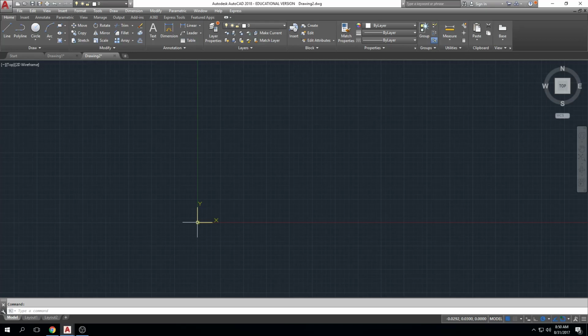When we look at our AutoCAD model space and we have these coordinates, when we move our cursor around, that is essentially telling you where in model space, using an XY coordinate, you are. So if I'm over 1, 2, and up 1, 2, 3, maybe I'm right there. This means I'm over 2 in the X direction, and up 3 in the Y direction. So 2, 3, and this is the X, and that is the Y coordinate.